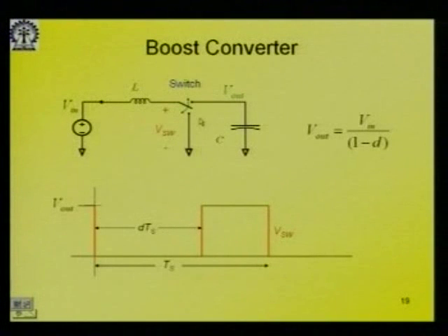The first period is the on period for the inductor. You can say the inductor is charged with a voltage V in here and this is 0. So the current will be rising at a rate of V in by L. And then once we put the switch back onto this, L di/dt plus V in together will be greater than V out and you will be pumping more energy into the capacitor.